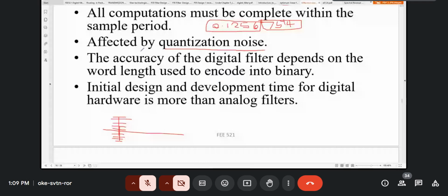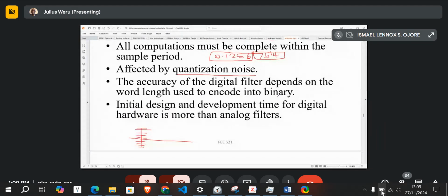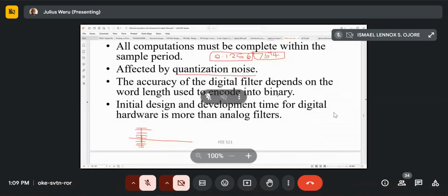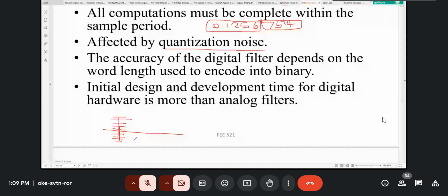But sometimes when we refer to quantization, we're also talking about the length of the word when you convert to binary. Because of storage, sometimes you limit the length of the word, so you cut off some part. Maybe I can give you a good example. If you are carrying samples and maybe they have something...